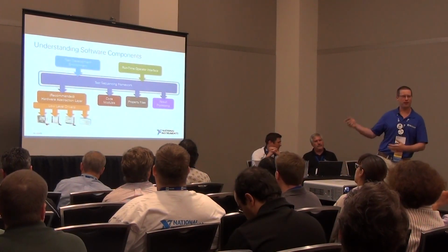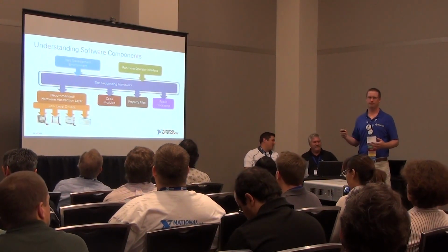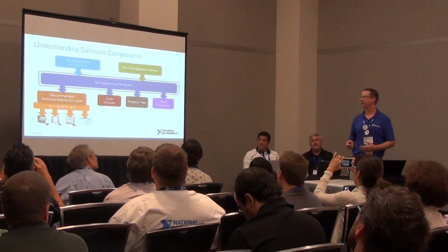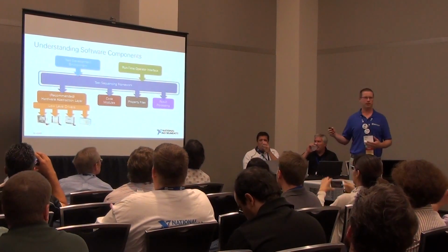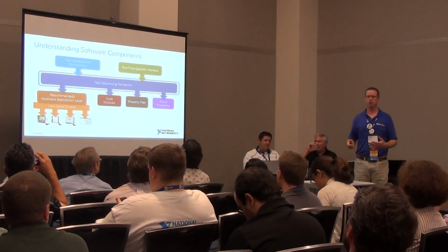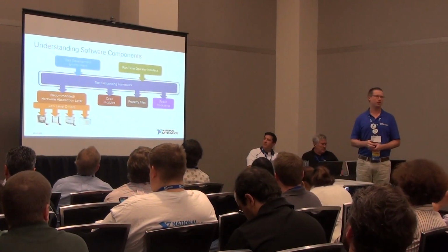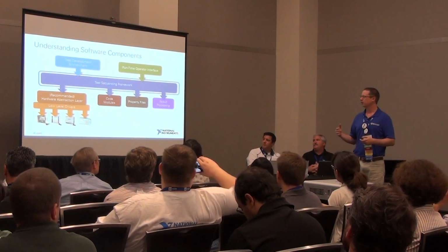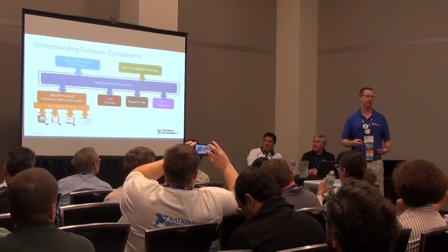So once you've defined your requirements and you've selected your hardware, it's time to implement your code. At the heart of your software is the test sequencing framework, which, typically, we're at an NI conference, usually I tend to choose LabVIEW or TestStand for this. But essentially, a test sequencing framework allows test developers to string together code modules and flow control in order to create a complex test sequence.